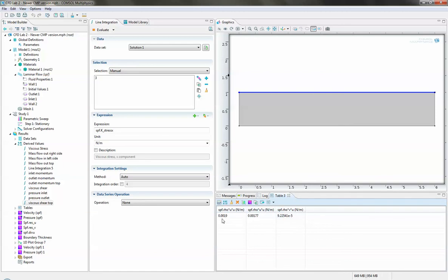So when you go to Reynolds transport theorem, that's in your textbook, the inlet momentum, because it's opposing the normal, is considered a negative momentum. The outlet is considered a positive momentum. So both of these outlets would be positive momentums. When you sum this number and this number, the outlet values, minus the inlet value, it should equal this viscous shear and pressure summation.